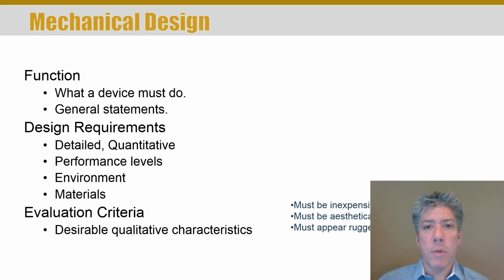It was really interesting. I was working for Amatrol, and I needed to design a device for holding bolts. We were going to have a robot automatically assemble bolts into a valve body assembly. And there are many different ways to hold bolts. One way is to palletize them. What that means is that the bolts are laid out in a known pattern so the robot can just remember which bolt it's at, go to a particular position, pick it up, and use it in the assembly.